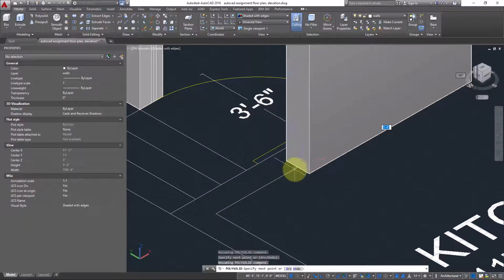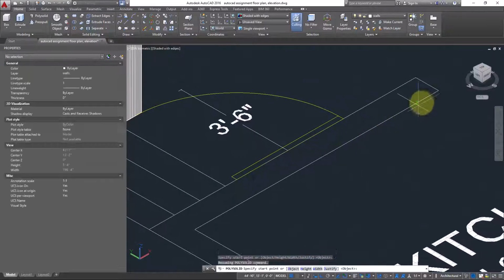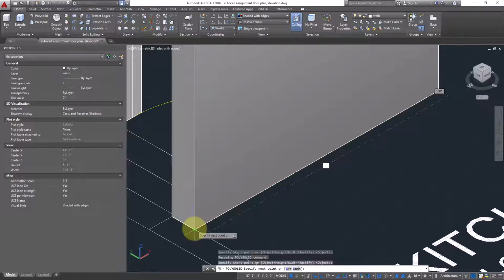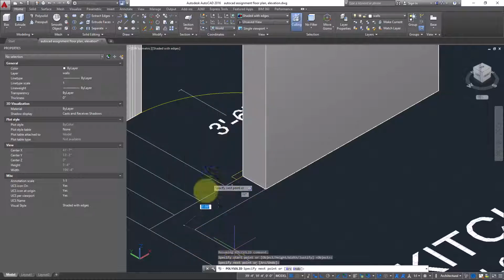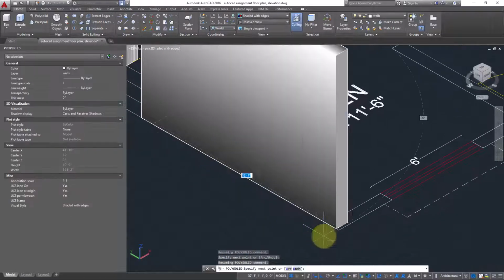So you can change the alignment as well. Again go to Polysolid, and now we have here justify. Before we set width and height, now justify, and I will choose left side. So my wall will now go in the left side direction like this. Now you can continue to create walls like this. It's easy, right?